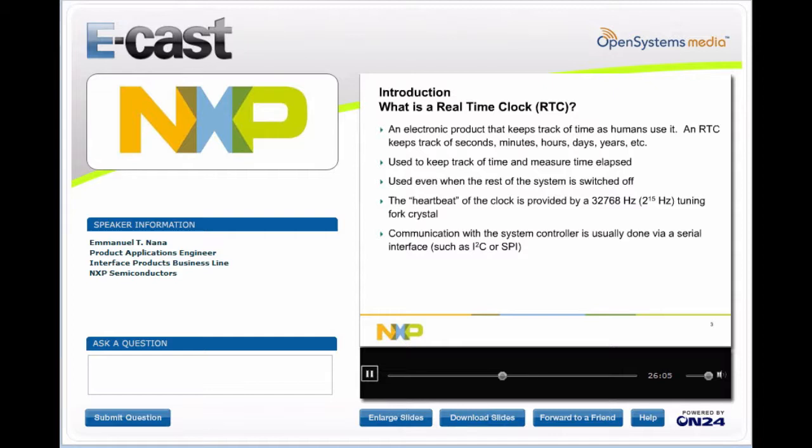And then there's also the reset output. The reset output basically works in conjunction with the countdown timer. Because the PCF2127 has the countdown timer, there is a reset output present in the PCF2127. The PCF2129 does not have the reset output or the countdown timer, but the watchdog function is present in both devices. And then the timestamp is also a function that is present in both devices.